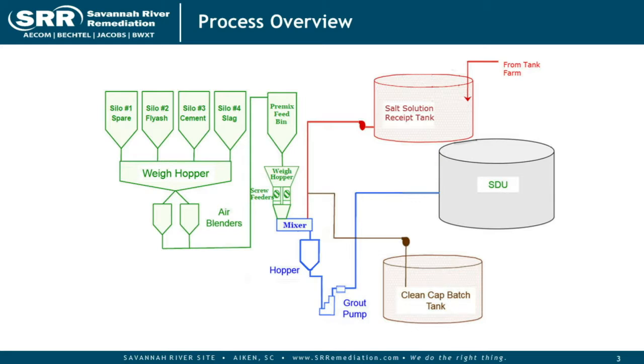So to start off, we'll start over here on the left-hand side of this screen. We have essentially a dry end part of the facility and a wet end part of the facility. Saltstone is a cementitious waste form that comes from blending the decontaminated aqueous salt solution from historically ARP and MCU, and in the future SWPF operation. We blend that with a mixture of dry materials that undergo hydration reactions to create a cementitious product.